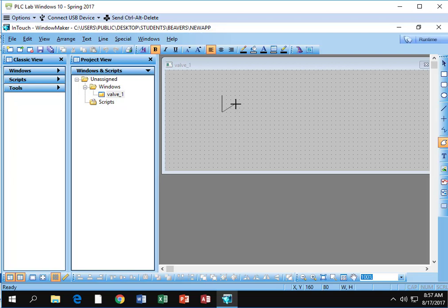Now click the duplicate selection tool, and this is going to make a copy of our original triangle. Once we've done that, we're going to click the flip horizontal, or you can also use the rotate if you want to, but we want to rotate that around and use the arrow keys to make sure the tips of those triangles are touching. Looks just like that.